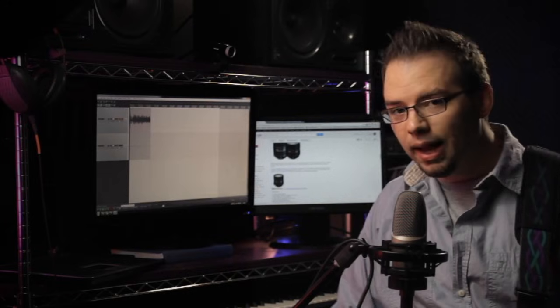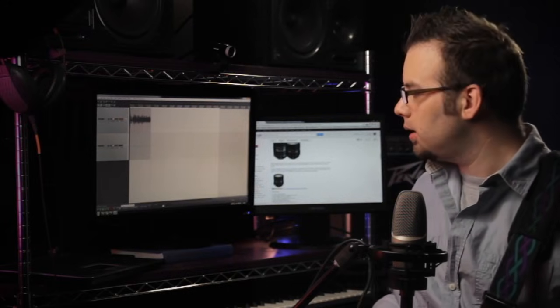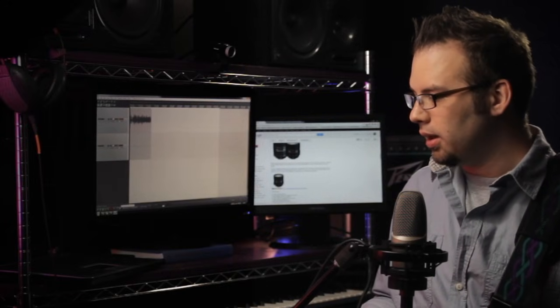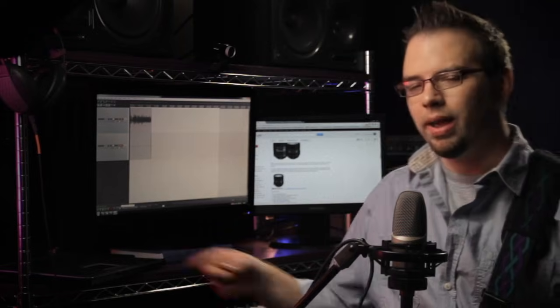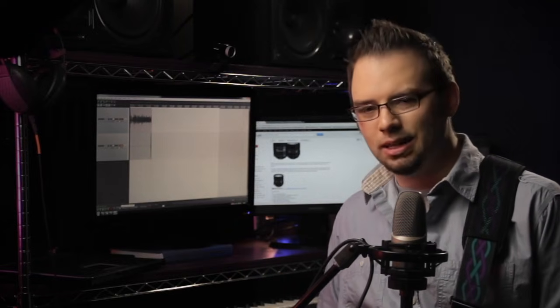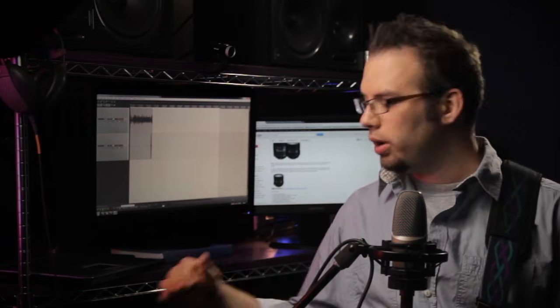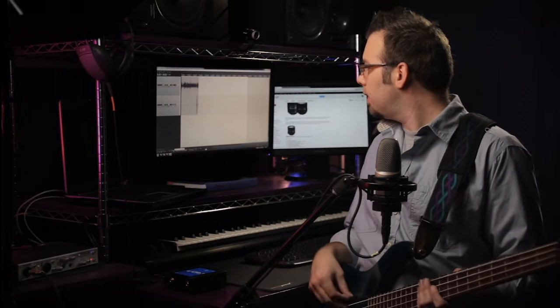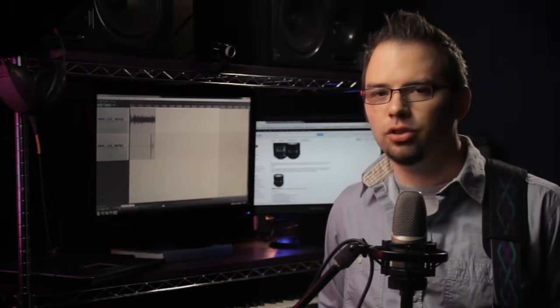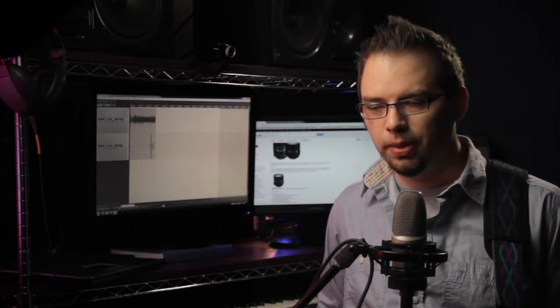and I turn the gain all the way down on the preamp, turn the volume up, watch the preamp right there. That red light that you see is clip. I'm sending so much information that even with the preamp turned all the way down, it's too much and it's clipping, it's going into distortion. That's bad. So I put the pad on there and then I turn the preamp volume up just a little bit. And now I get a nice juicy signal and it's not so much that it's pushing into distortion.